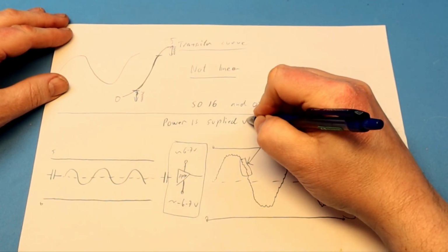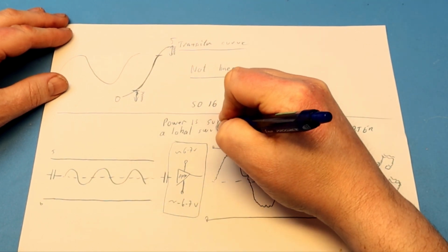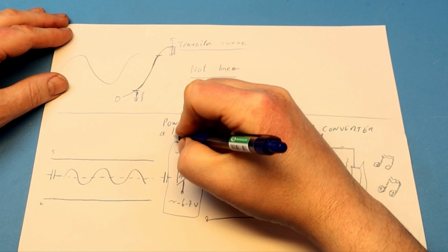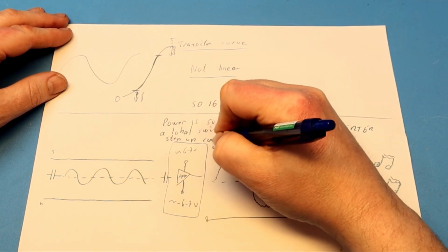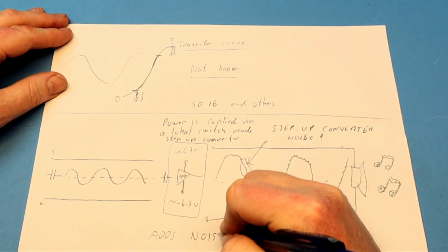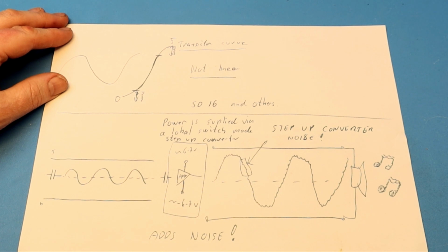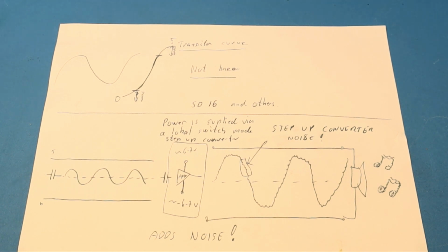It's because there's so much noise introduced in the analog part of the signal. It's partly because of the step-up in the amplifier circuit, and partly because it's not handling the noise from the bus very well. And of course, if you have a 10 volt signal, you have a much better chance of getting a good signal to noise ratio than if you try to do everything within 5 volts.